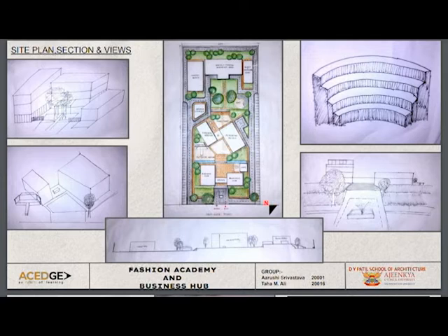Straight up, we have a hostel block which is lifted one floor above the ground level to create a wind tunnel effect, making its way to the site and cooling the complex. To the right from the hostel, we have the principal and guest house. This is the site section in which you can see the levels and the heights of the blocks.